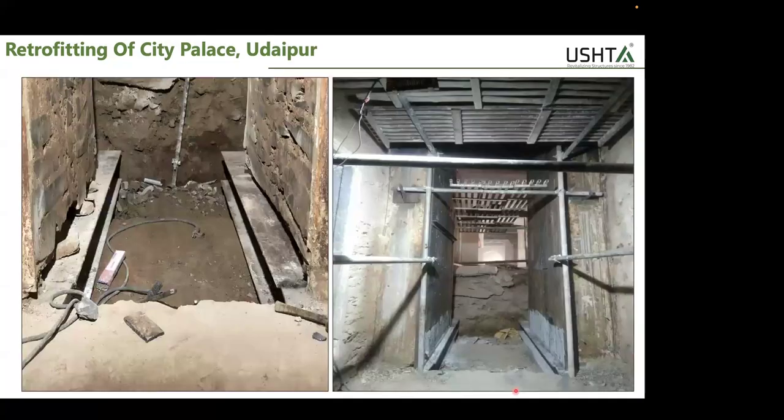Now what we realized was one problem was that after we went about 7-8 feet down, we realized there is no foundation for this wall. So how will the load transfer happen? So then we prepared a transfer girder here, created foundation on both sides, and transferred the load of this specific wall to that girders through this girders.